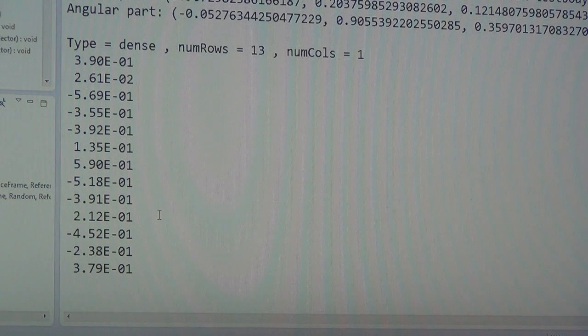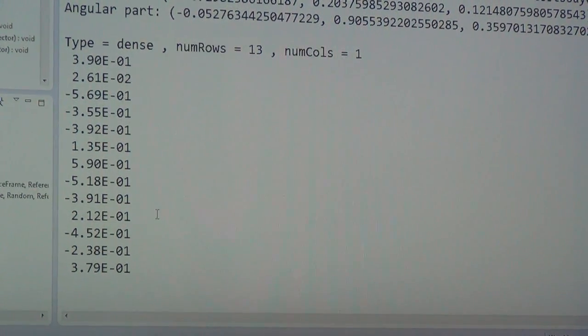Yeah, so now we're able to, for any mechanism we want, compute the velocity of any point on the end effector with respect to the base, and also calculate torques that achieve a certain wrench at the end effector, basically. The Jacobian is just pseudo inverse.